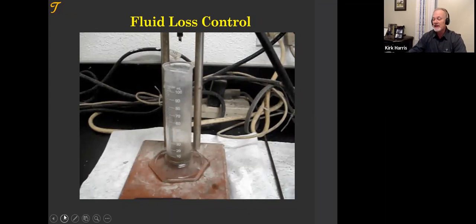We tested unconsolidated sands that would have 3,000 millidarcy, and it was hard to get water to come out of them. But we can get a lot of water to come through screens. It's a 325 mesh screen. For ultrafine cements, we use a 600 mesh screen because the cement will actually go through the screen of a normal one.